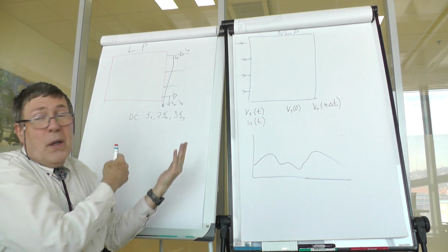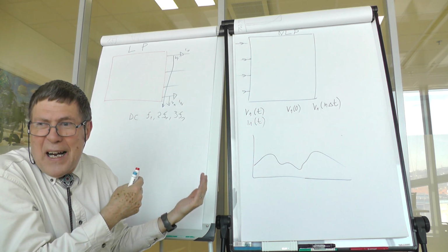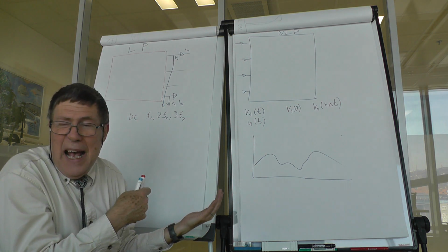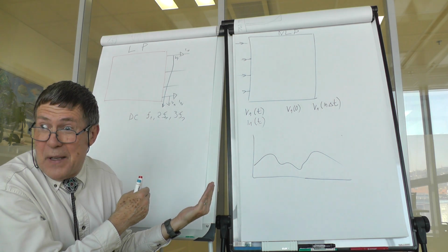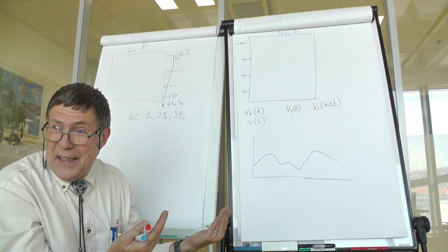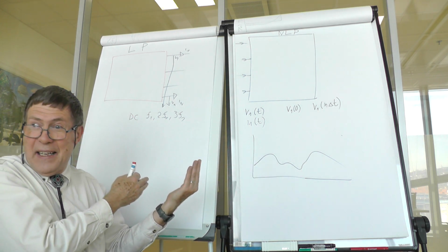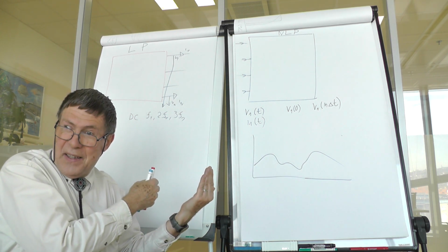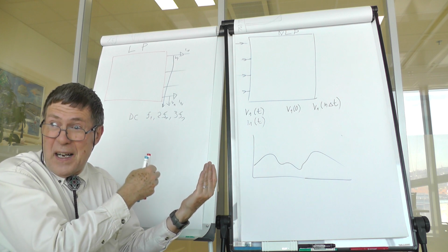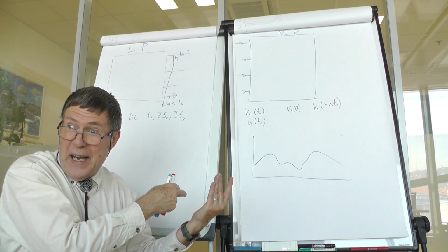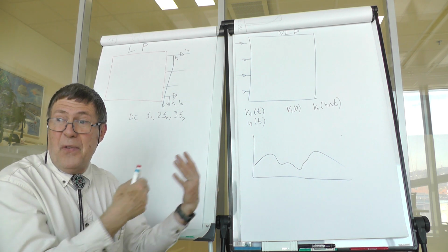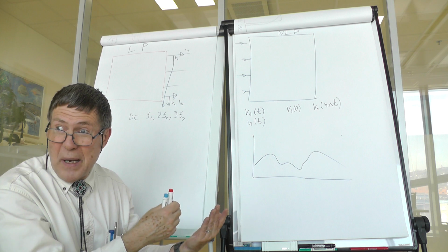Now, what if there is an important harmonic at 18 times the basic frequency? Well, if this is true, remember I will get it mirrored inside, and it would pretend a much stronger 14th harmonic and distort its phase, which then would prevent me from reaching harmonic balance at all.